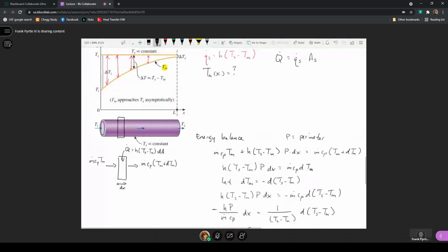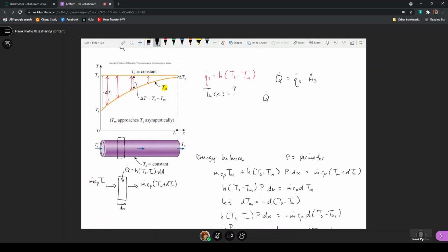And we can write an expression of the heat transfer rate that is this average heat transfer coefficient times the entire surface area on the inside of the pipe, multiplied by an expression of delta T_LM, as it's referred to in your text. And that is what's called the log mean temperature difference.